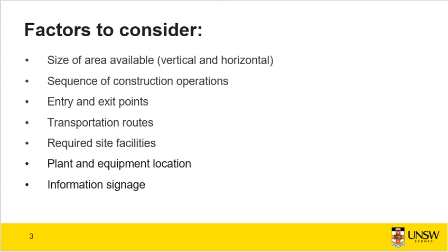Four excavators of different sizes and capabilities were used to cut existing sand and fill imported crushed material to construct a working platform for a CFA piling rig to operate safely. Laydown areas are also established for the delivery of procured materials, temporary storage of supplies, and assembly of reinforcement and construction equipment.